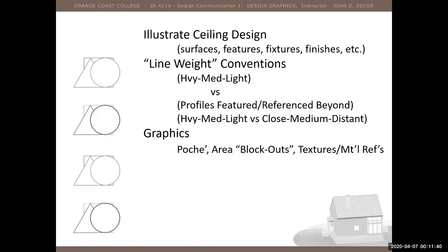So it is important that we think about the line weights. Now, those same rules apply. The light line weights that are used for heavy, medium, and light need to be applied to the drawing in a way that makes sense. So let me just suggest to you that as you trace the floor plans, think about what you're drawing and look at it as if it were looked at through some distance.